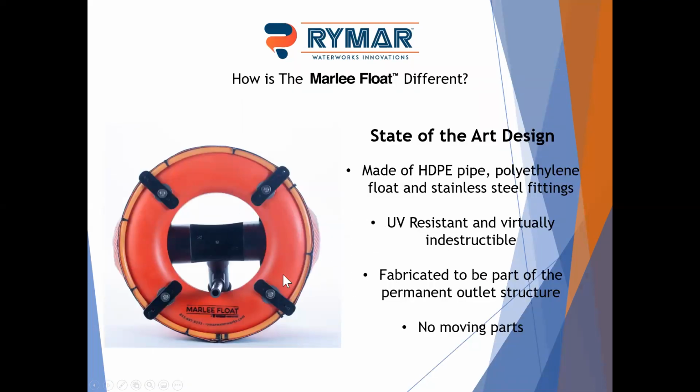Again, our product's made of HDPE, so the floats are polyethylene. It comes with polyethylene pipe. There are a couple of PVC parts that are hard to get in HDPE, but they're all Schedule 80, so a heavier grade of PVC if they are. And there's no moving parts or anything to get stuck. It is very UV resistant, a very, very durable product.